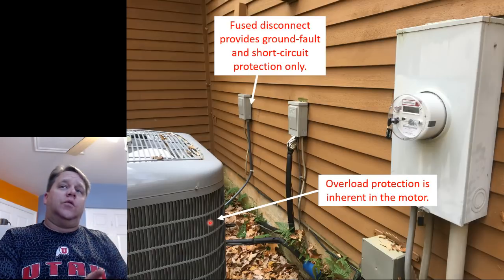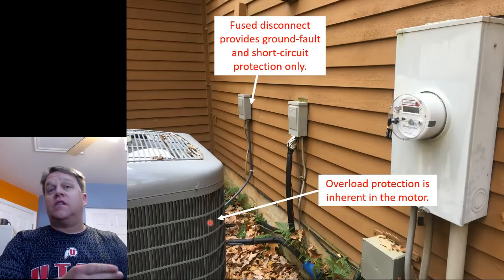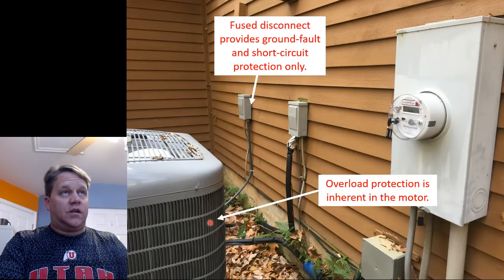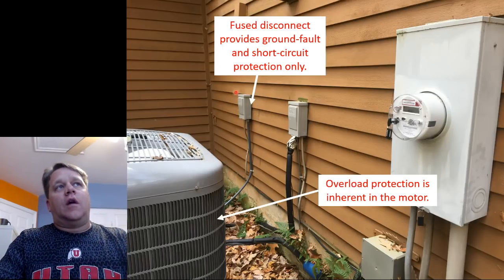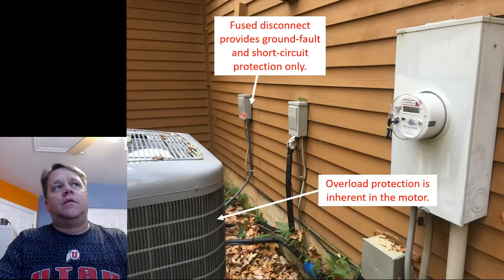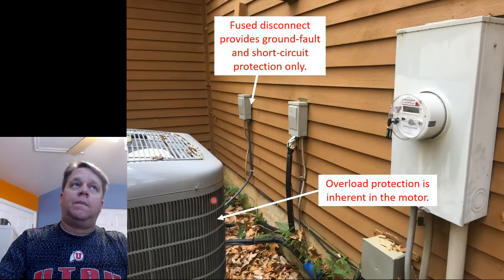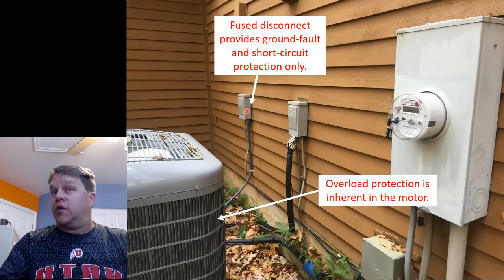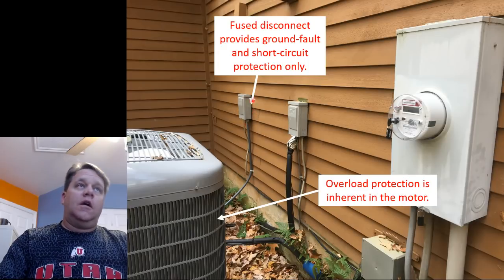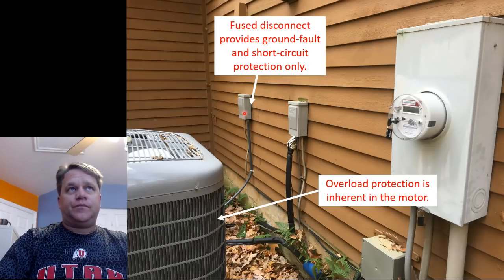That is not how we do it for air conditioners. It's not how we do it for motors. It's not how we do it for feeder taps. It's not how we do it for transformer secondary conductors. For those 4 circuits, we do it this way. We provide ground fault and short circuit protection upstream. We provide overload protection downstream. Okay? So I need you to understand that. Overload protection is done by the motor. Ground fault and short circuit protection is done by the fuse disconnect or the circuit breaker in the panel if it's a pull-out disconnect. Overload protection at the motor, ground fault short circuit protection upstream of it.